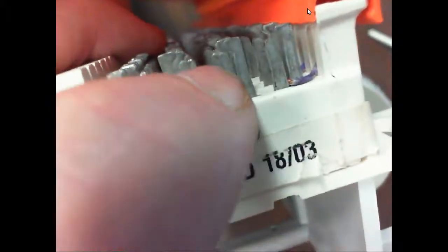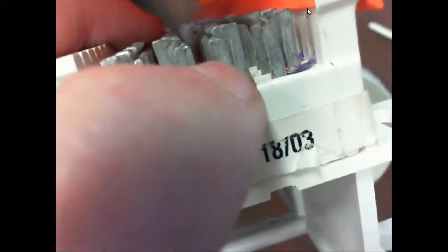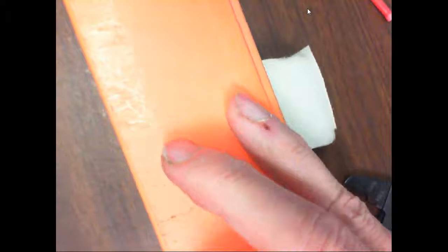Somebody's lost the. So on the 66, we're set on there now. What we would do, when you don't strip the wire, which is so cool, what happens is the block itself has blades on it that's smaller than the wire gauge itself. So what it actually does, it actually bites. Can y'all see the way it gets narrow as it go down? So it literally bites into the insulator. So we don't have to strip the insulator. We'll find out that this is true. This is true on our network cables also.